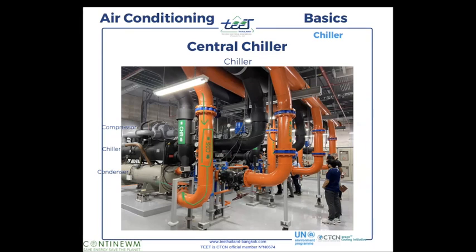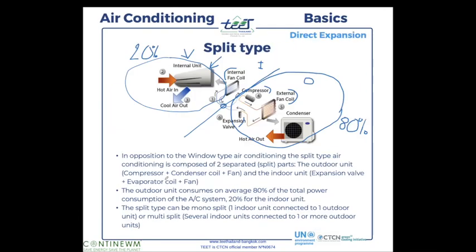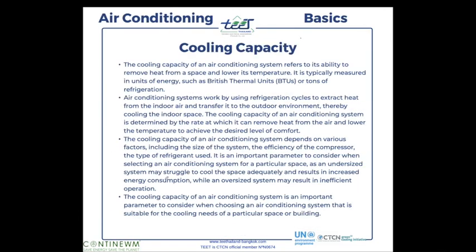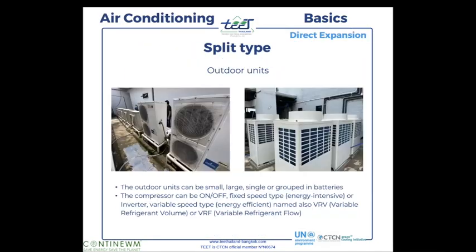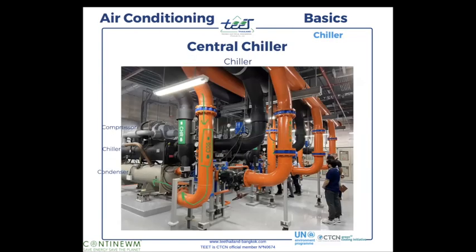So here you see this is basically a tank. Inside, you have the condenser, the same coil that you see here, but instead of being in the air, you have it inside this tank. Here you can see this copper conduit, the one that I highlight on the left. This one is the refrigerant fluid. You can see it's much bigger than in an air conditioning, but you have to cool a full building.